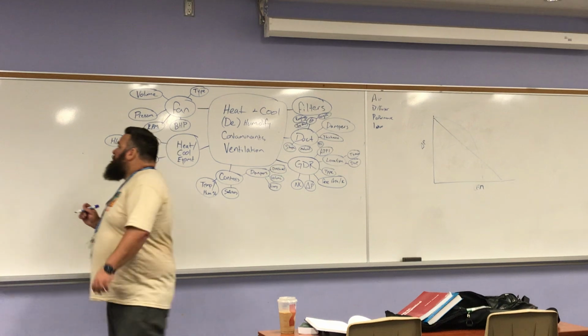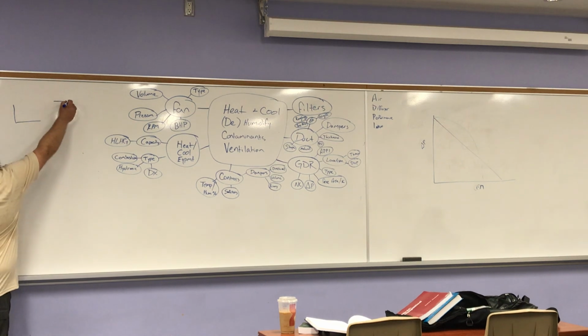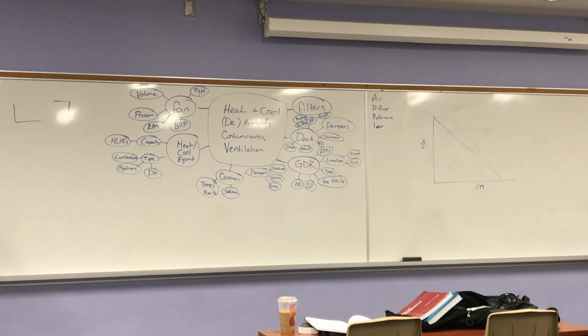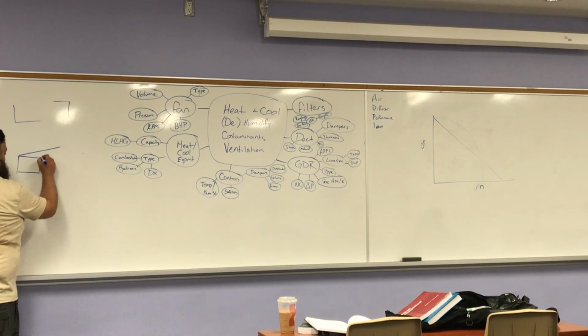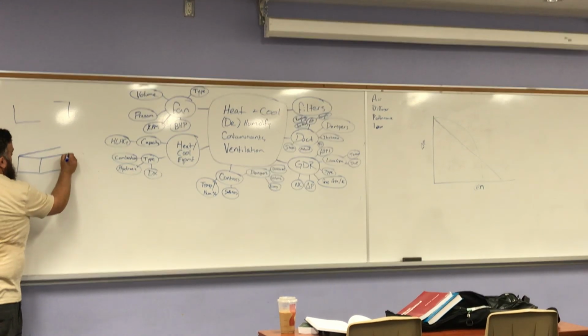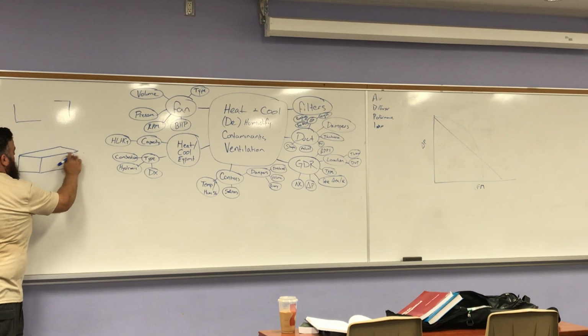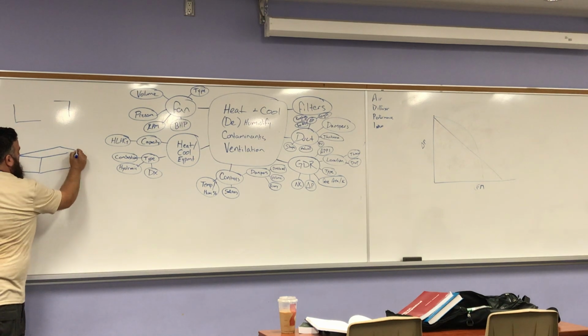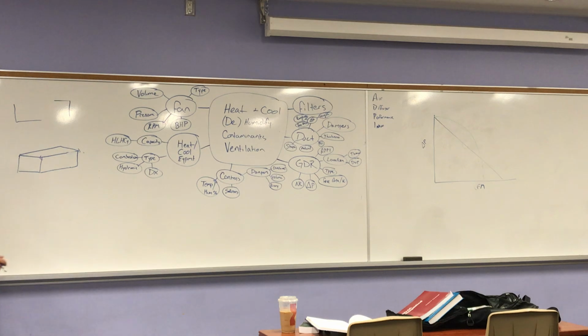When you buy rectangular duct, you get it in two L shapes, okay? Like that. So they pack together quite well. And they have what's called a Pittsburgh lock. So if you looked at the duct, that's my duct. Sorry, drawing freehand isometric. Okay, that's my duct. So this is the Pittsburgh seam right here.